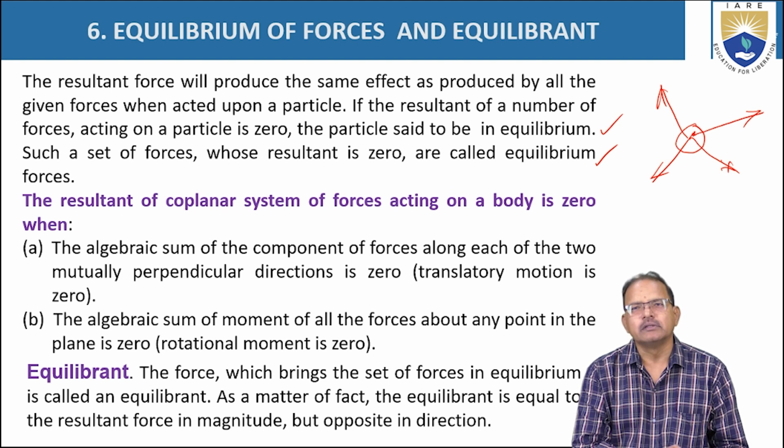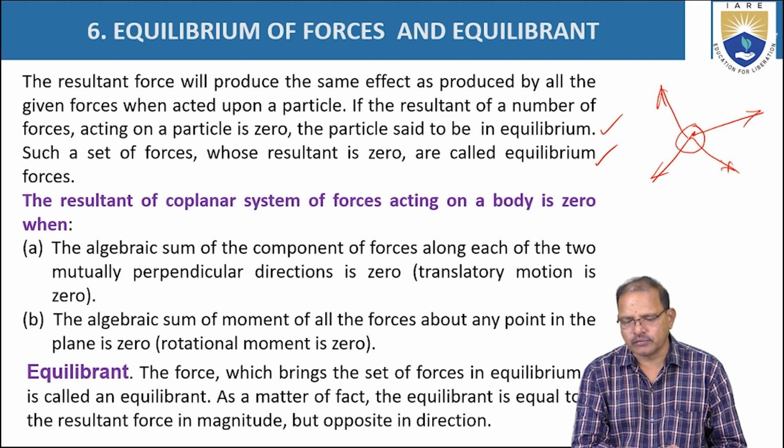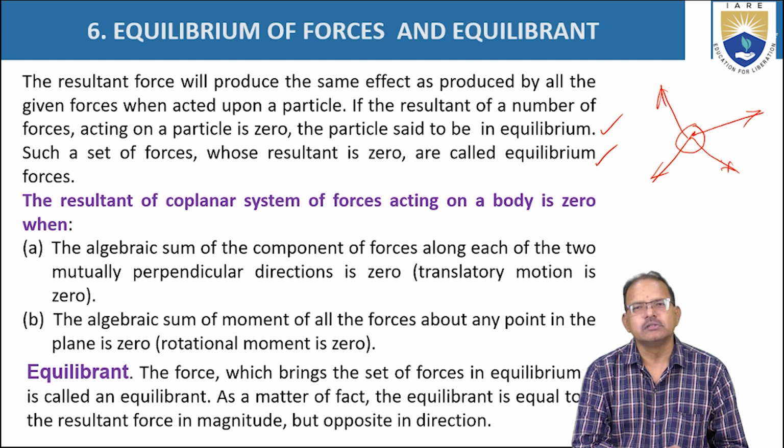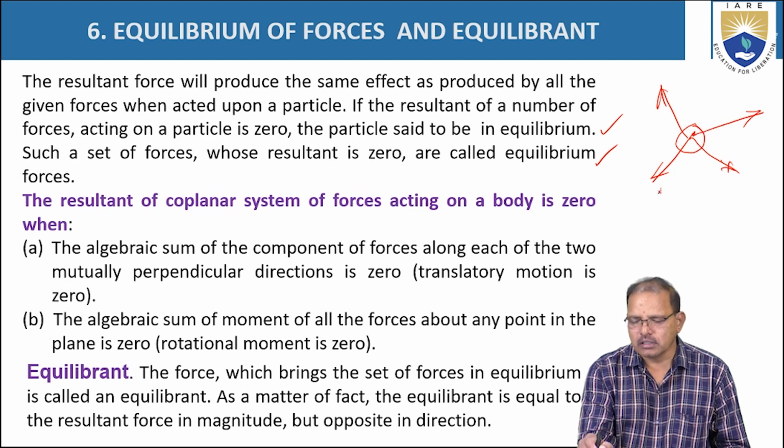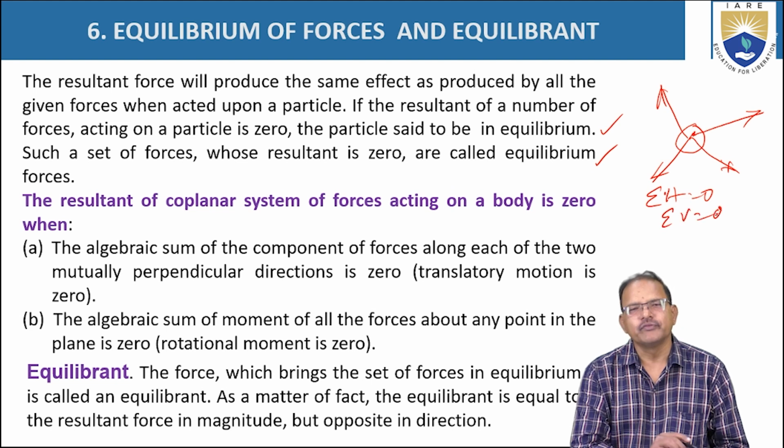It will happen because according to the resolution of forces, or the analytical method to find the resultant of a several force system, the algebraic sum of all the forces acting in the horizontal direction should be equal to 0, and also the sum of the components of the vertical forces should be equal to 0. That means sigma H is equal to 0 and sigma V is also equal to 0.